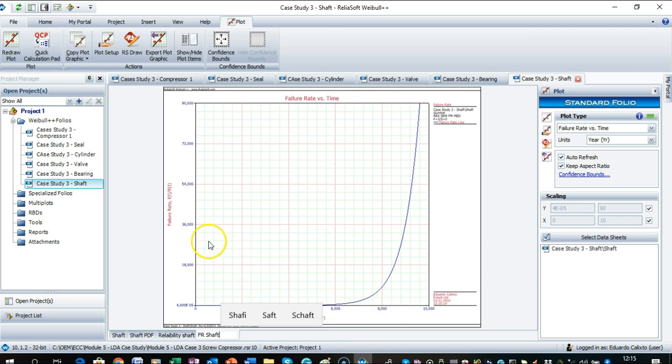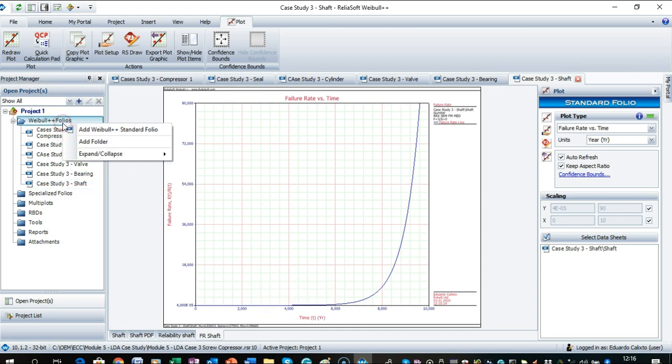result that we've got to use for preventive maintenance inspection. We have exactly the time that the failure rate is starting to increase, and then we can define that, at least for our first inspection. Then, of course, we maintenance engineers have other methods such as predictive, online monitoring, and prognostic health management that even define the new expected time to failure and the remaining useful life, and based on it, you can always update the inspection interval of 3 years. But based on reliability, we got this value, and now we create our next case.